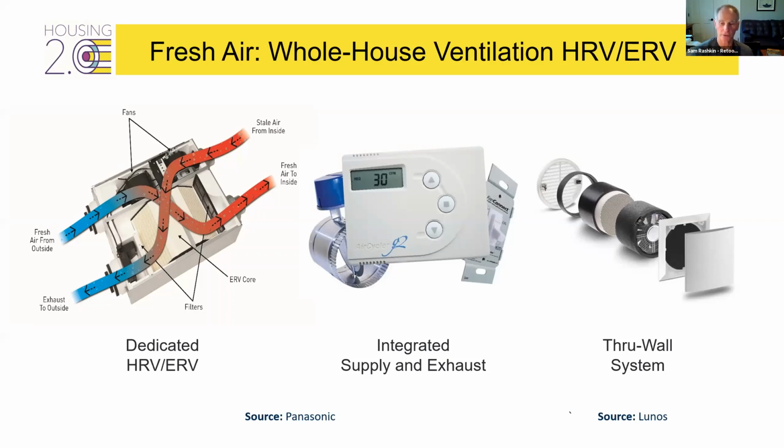And there's some really interesting technology. This through the wall system is really great for small apartments because I don't need ducts. It's really low wattage, 90% heat exchange, about 20–30% moisture exchange, only like 8 or 9 watts. It's almost like a night light, and it's incredibly quiet. It pulls air in, out, then stops, then pulls outdoor air in across the ceramic module. And it's a really good option to consider for small units, particularly multifamily housing, where it's really hard to figure out the ductwork and how to do balanced ventilation.